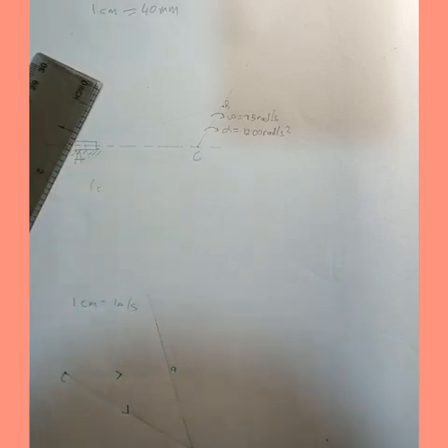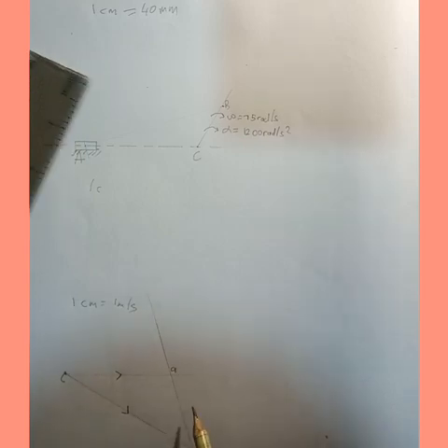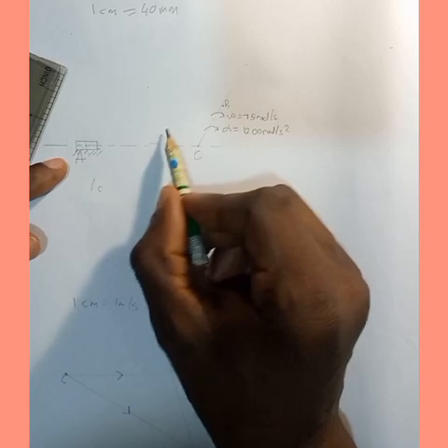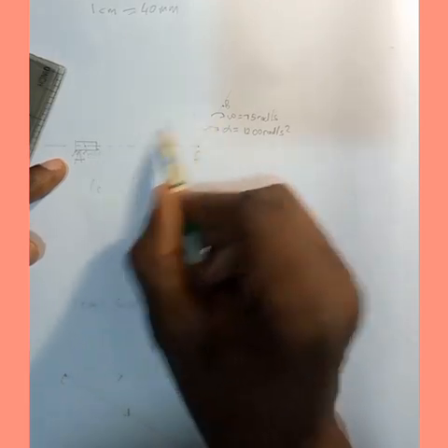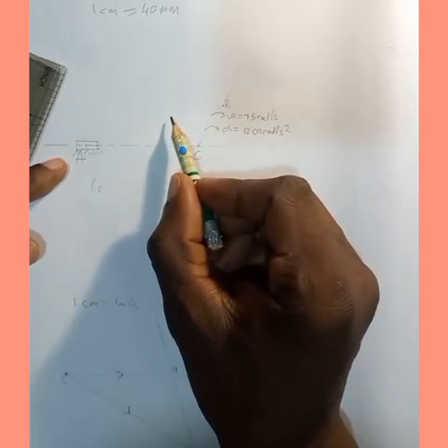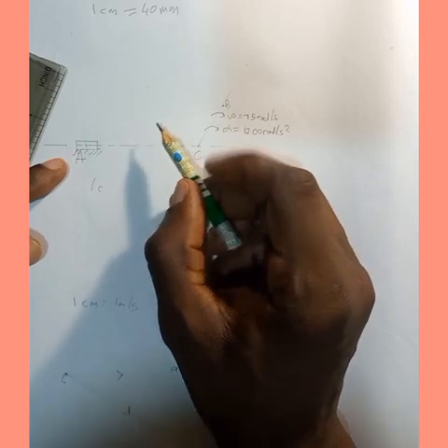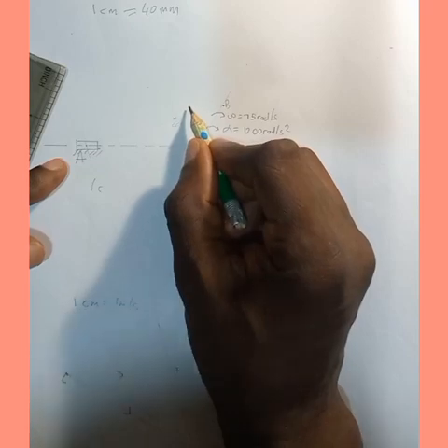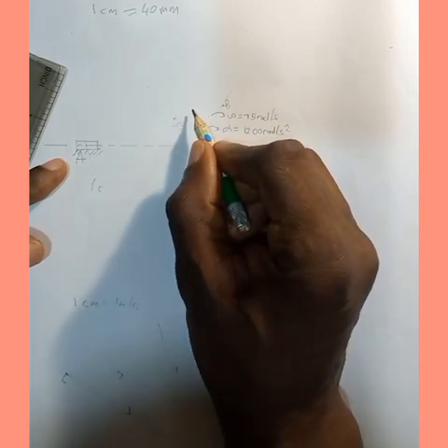So now we need to find the velocity of point G. On the configuration diagram, your G is somewhere on your connecting rod, but the distance of point G here is 100. It means that from here to here is 100 mm.